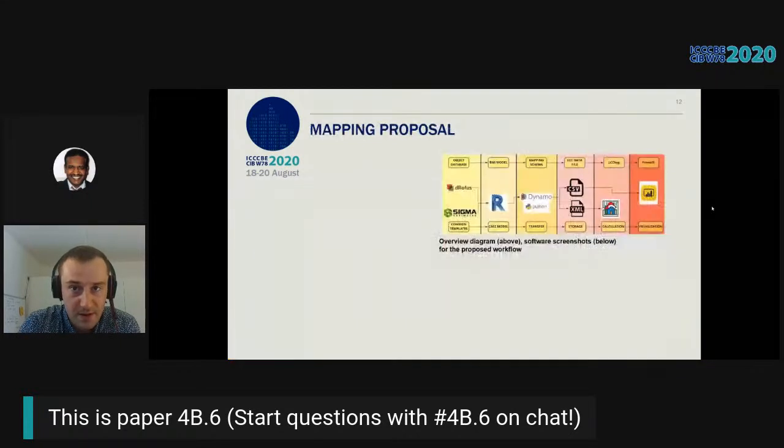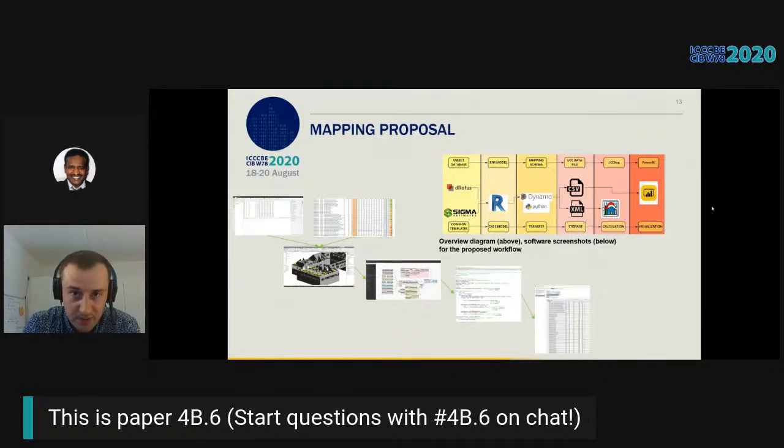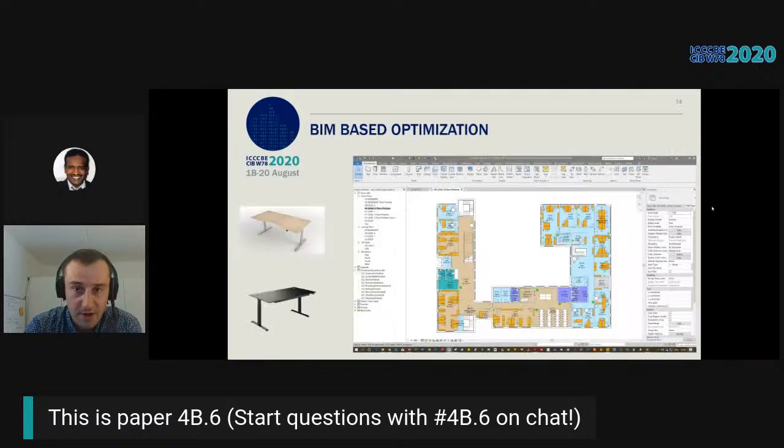So we then mapped the costs with the model, and then we extracted quantities using Dynamo, and then we used the elementary module to serialize an XML file using Python, and exported a CSV table and SVG graphics for the Power BI data display: the CSV table for the graphs, and the tables for the plans. So let me show you an example of how it works.